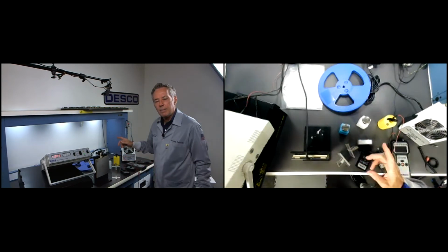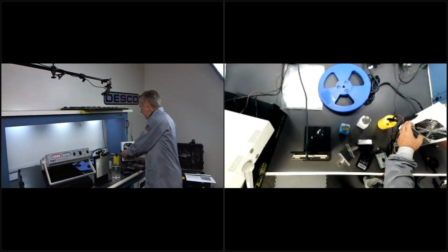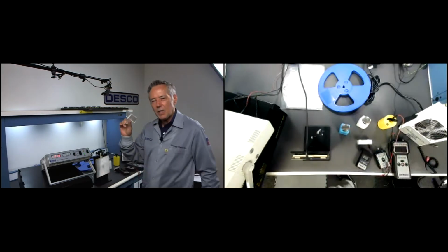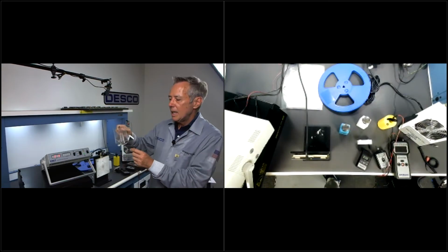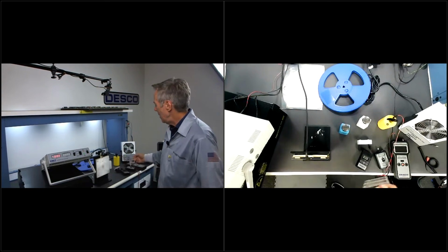So I'm going to show you now how we work with ionizers, for instance. Let's pretend that this plastic paddle is the plastic case of my cell phone. A cell phone's only that thick. There's no way I could keep that circuit board more than 1 inch away from that plastic cell phone case. So that's now a process required insulator. Again, I'm going to charge this up. I'm going to show you that I got a charge, but now I'm going to hold it in the presence of this ionizer. And I come back here, and you're going to see that it's knocked the charge down. It's got 3 volts on it, which is negligible.